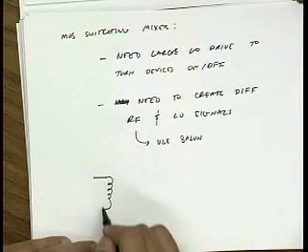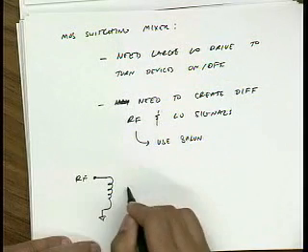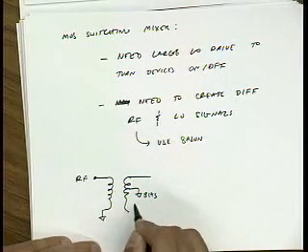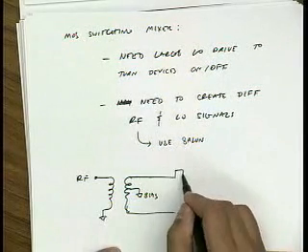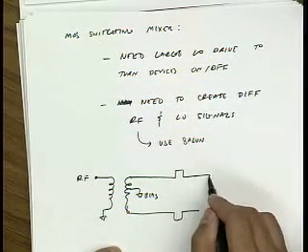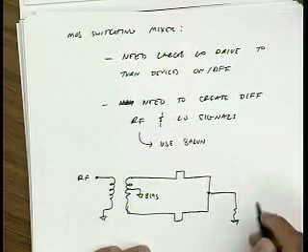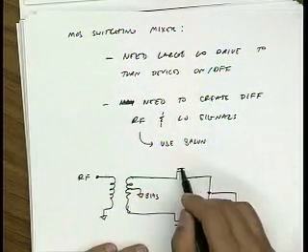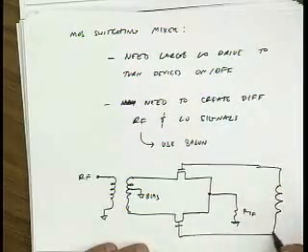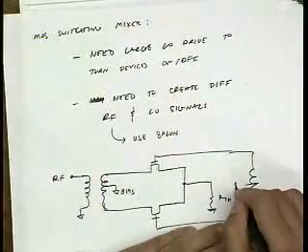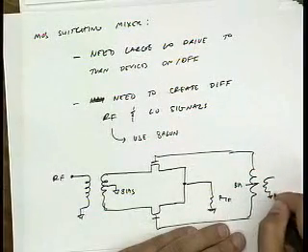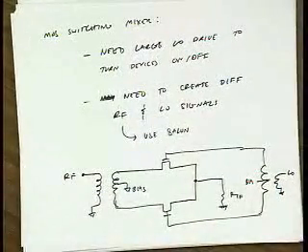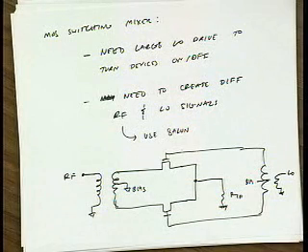So for instance, I could come in with a single-ended RF, convert it to a differential RF, actually pick the right bias point for my switches if it's not ground, and I could likewise drive these gates with a single-ended LO. But usually your LO can be made differential. You're going to have a differential LO buffer, so that's less of an issue. Okay?